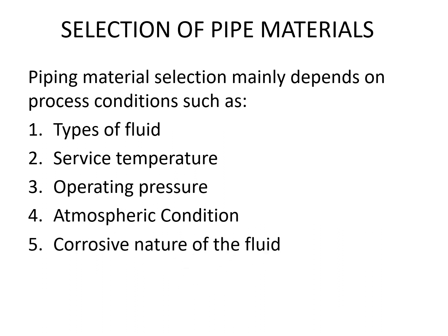Atmospheric condition, why I have put it here, is because, for example, if you have a pipe in an atmospheric condition where the temperature goes beyond minus 25 or minus 40 degrees centigrade. If you have heard about the design condition which we call MDMT, minimum design metal temperature. If your MDMT is not colder than the atmospheric condition, then your pipe will become brittle and will fail. Hence, it is very important to check the atmospheric condition before selecting pipe material.